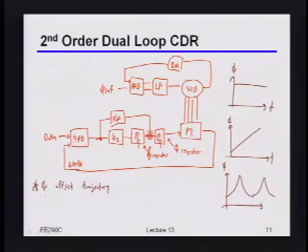How do you do that actually? Say that again? How do you do that spreading? Okay, there are lots of different ways you can do it. Among the choices of techniques are things like adjusting this divide ratio dynamically, and usually using some fractional-N PLL for that. There are similar examples that we'll walk through in a second where, let's say you had some phase interpolator at your output, and then instead of tying it into a feedback loop, you had some deterministic trajectory you created through that phase interpolator. But basically pretty much anything that mucks around with the PLL, you can use to create really weird looking trajectories, especially if you know what it is that you want to do. Not to say that it's an easy thing to do, but there are lots of different ways that can potentially be done. Okay?